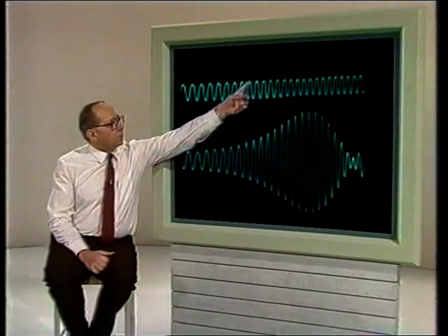Well, that output response curve is rather intriguing, so we'll just take a closer look at those oscilloscope traces. Here is the input disturbance. Constant amplitude with steadily increasing frequency. And you can see this effect by the bunching together of the sine waves as we go to the right at higher frequencies.